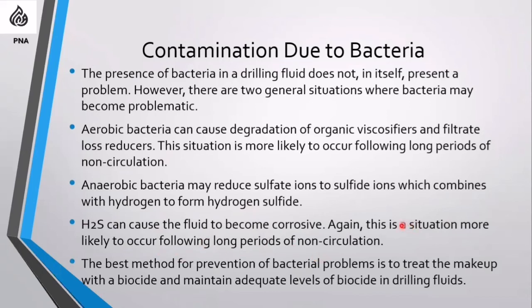So the best method for prevention of bacterial problems is to treat the makeup water with biocide, and maintain adequate levels of biocide in our drilling fluids. From time to time we have to add some biocide to our mud in case of stopped circulation for a long time.